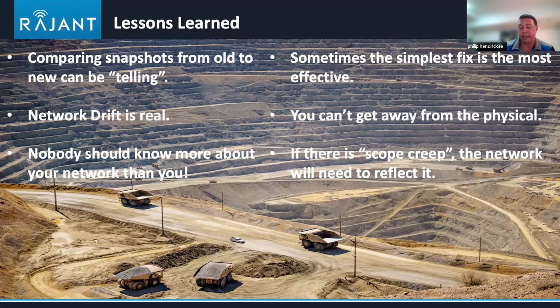And in the case I showed you before, the simplest fix is the most effective. We had people chasing noise and different sources of RF interference and all that sort of stuff. And in the end, all we did was just move a trailer with a point-to-point link, and we solved the problem. Okay. You can't get away from the physical aspects of mining, especially in surface mining.